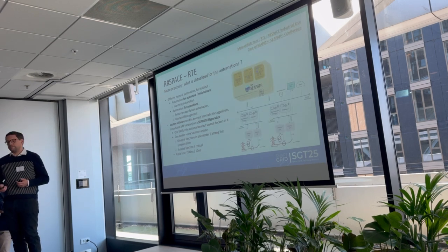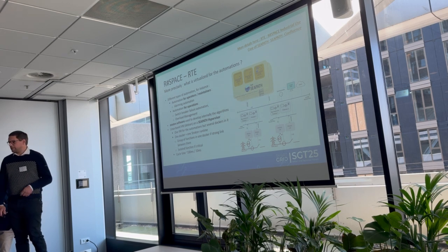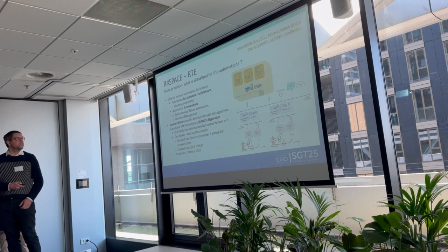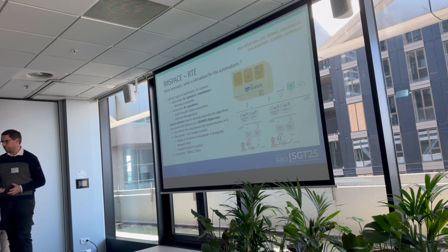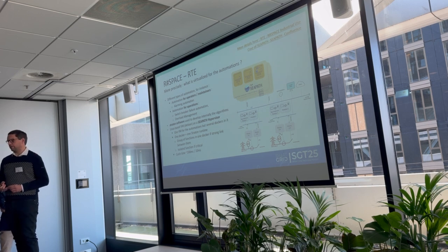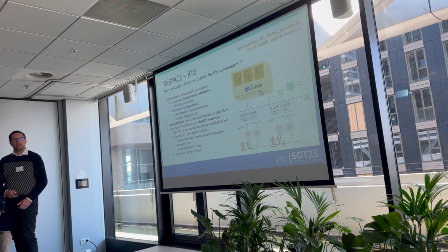So more precisely, what is virtualized for these particular automations? We have different types of automation needs. So for instance, automation for operators, so alarming automations, basically doing some grouping of information. But we also have automations for operations, for instance, the switch breaker failure automation or the overload management. They are all done in virtual IEDs. To do so, we use Straton software to develop internally the algorithms. That is to say, the engineers at RTE are using Straton software to write the code, in fact. And then we are deploying it in the CPaaS infrastructure.